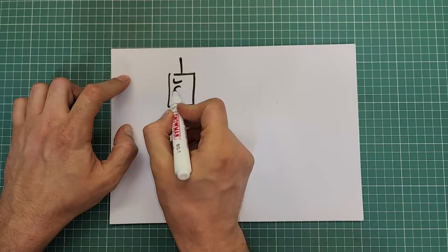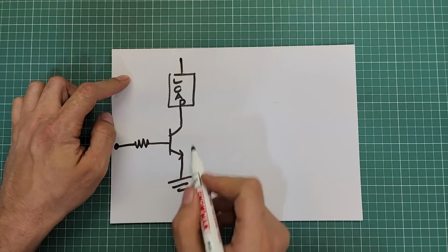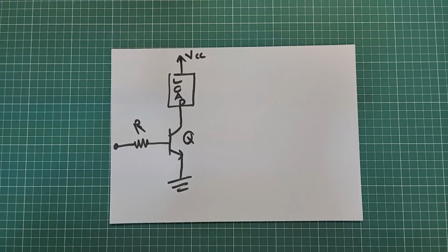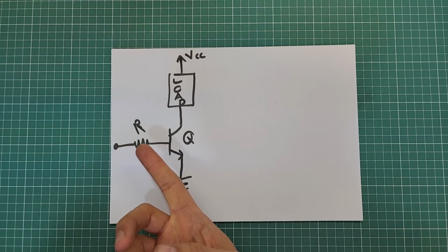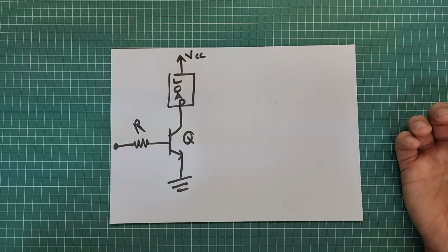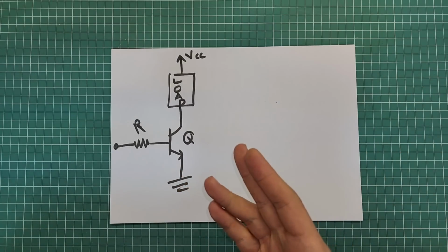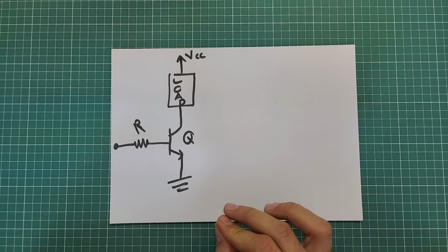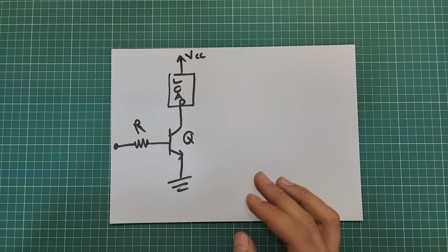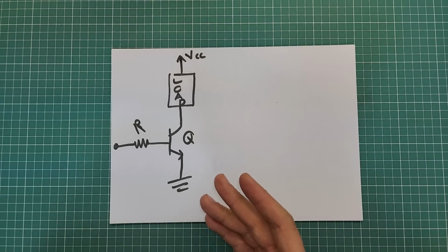Before answering this question, it's better to know the consequences of a bad resistor value. What could go wrong if you pick a bad resistor value? A bad value for this base resistor is one that works, but there are other values that work better. A good value should put the transistor deep into saturation in a way that the transistor can't go back to the active region easily. What are the active or saturation regions, you may ask?